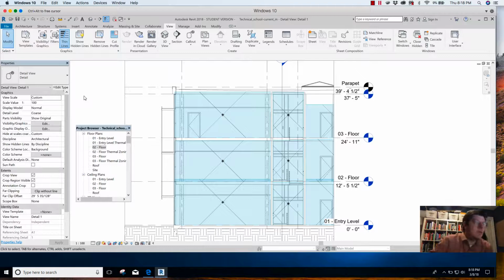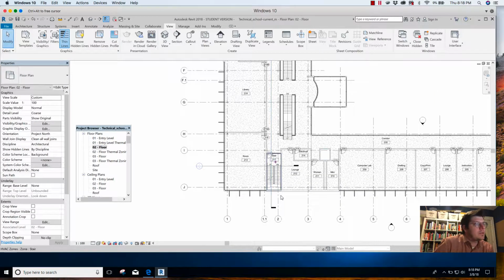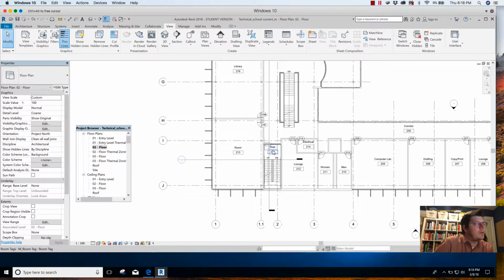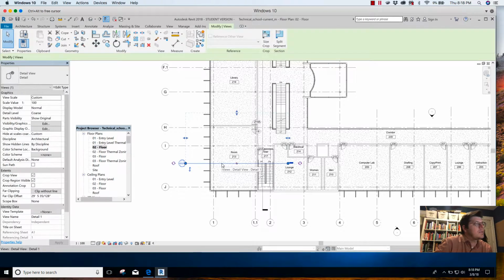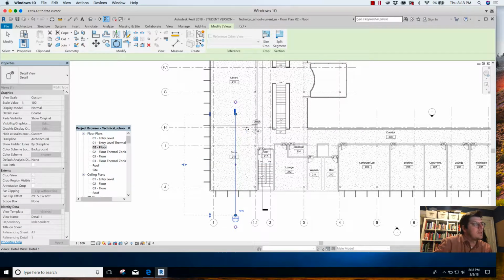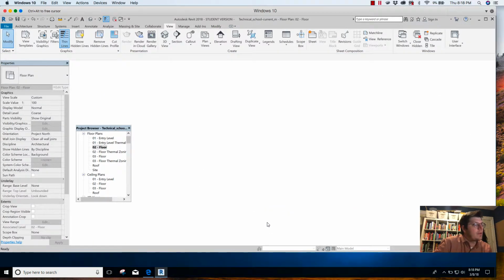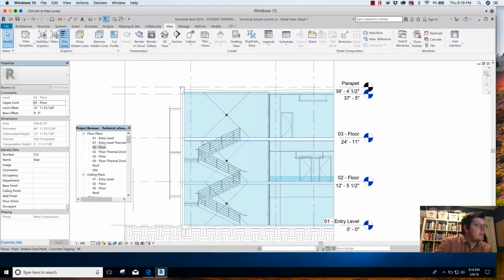So we would want to do that. I think, let's see, if I go back to floater, there's a few different ways to handle stairwells. You can either define the whole stairwell as one room, or I'll do another section. I'll just rotate this one. Or you can define it based upon each level, more or less. It's up to you. I've done a little bit of testing and I found the results to be nearly the same, but the key is, we can see how I've got these gaps between these rooms.